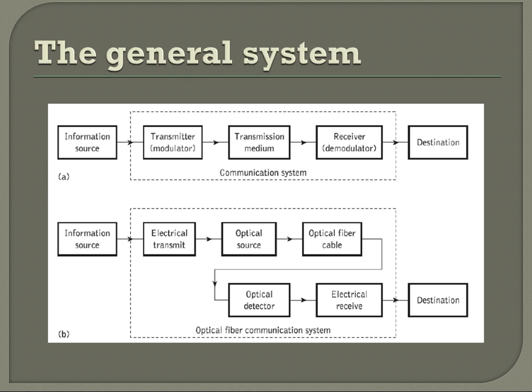The transmission medium consists of an optical fiber cable, and the receiver consists of an optical detector which drives a further electrical stage, hence it provides a demodulation of the optical carrier. Photodiodes, examples are PN, PIN and avalanche photodiode, and in some instances phototransistors and photoconductors are utilized for the detection of optical signal and the optical to electrical conversion.